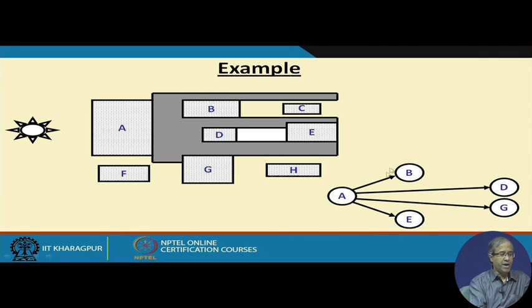And when you add these edges, depending on the design rule, you can also add the weights. So, A and B, minimum how much separation it should be. Suppose this is polysilicon, this is also polysilicon, this should be 2 lambda. Similarly, A and D, how much minimum separation? A and E, how much separation? Like this. So, this you repeat for all the blocks and you will be getting all the edges in the graph, right. So, this is the basic idea behind generating the constraint graph.